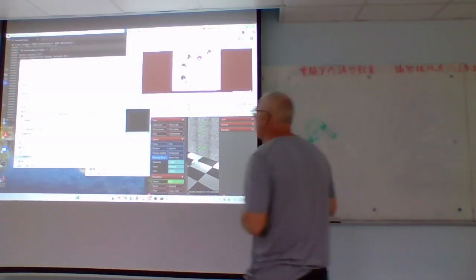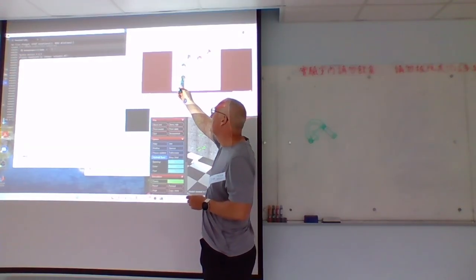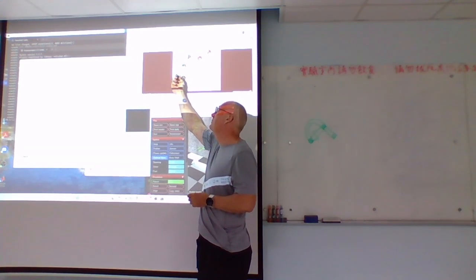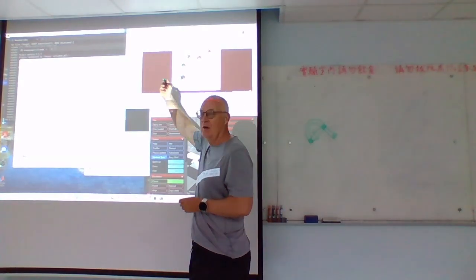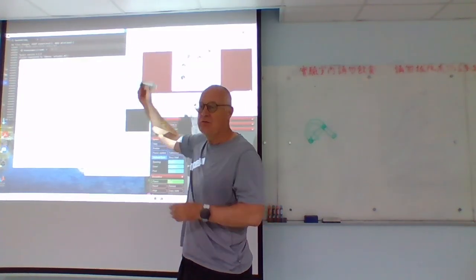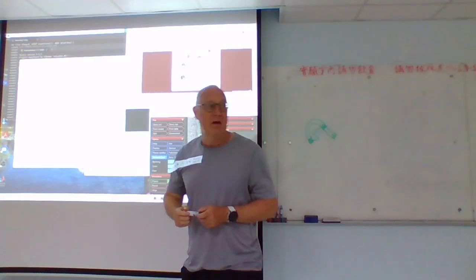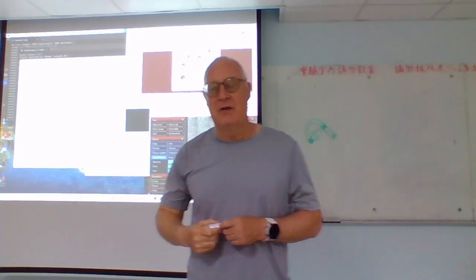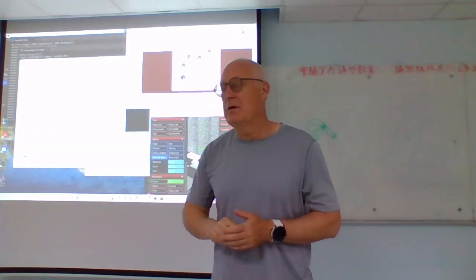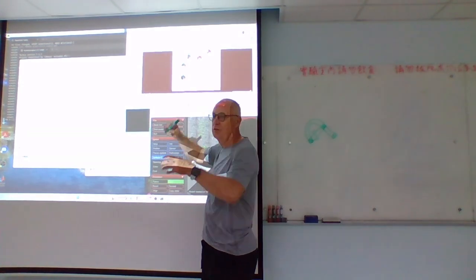It doesn't completely specify the coordinate system, because even if I say that z is the axis of actuation, I still have a lot of flexibility where I put 0. Anywhere on this axis, I could put the coordinate system, right? It doesn't have to be at the horn of the servo. And in fact, if you follow the Denavit-Hartenberg convention, which is a more stringent convention that I'll talk a little bit more about later, then most of the time it's not where the servo horn is.